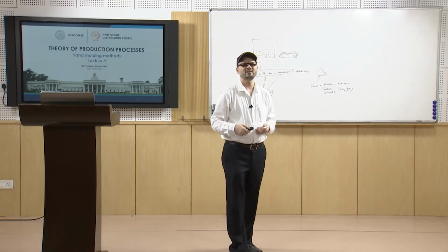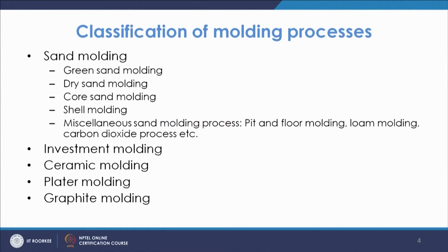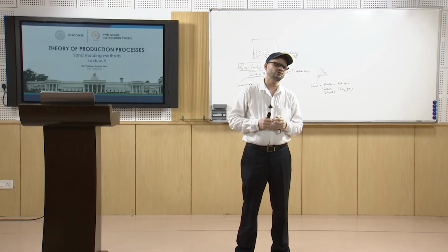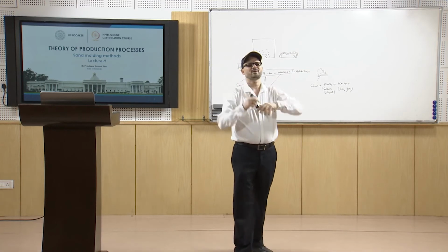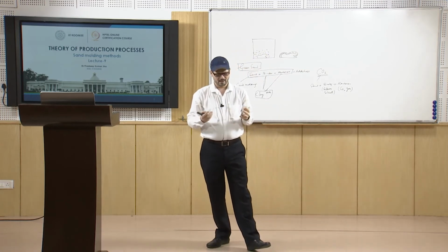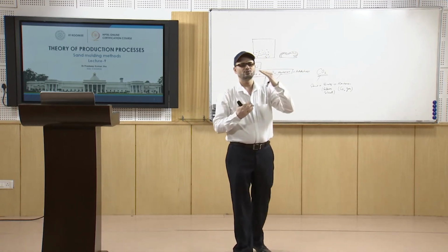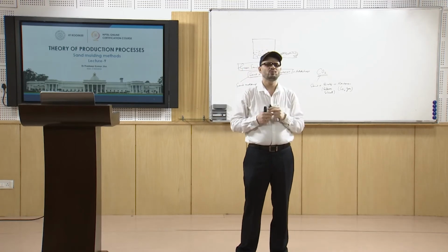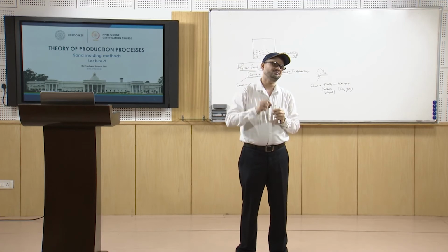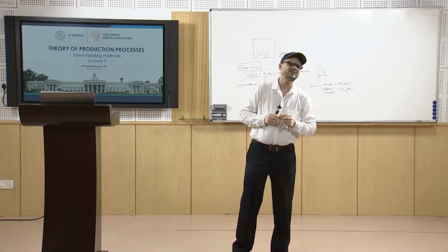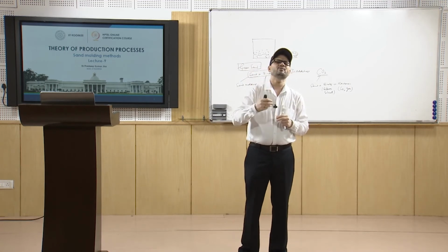Ceramic molding is done in the same way; in ceramic molding, ceramic is used. In investment casting and ceramic molding, the heat extraction rate is quite slow. So the metal will go into the intricate cavities, and you get very fine details in the case of ceramic molding.